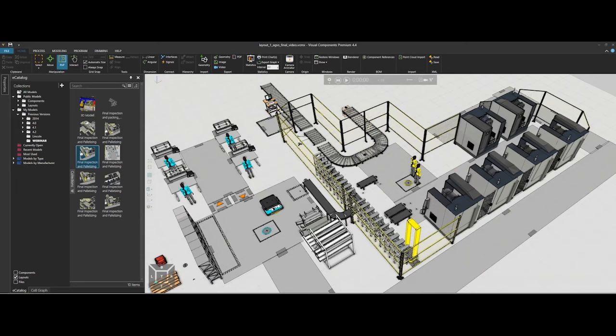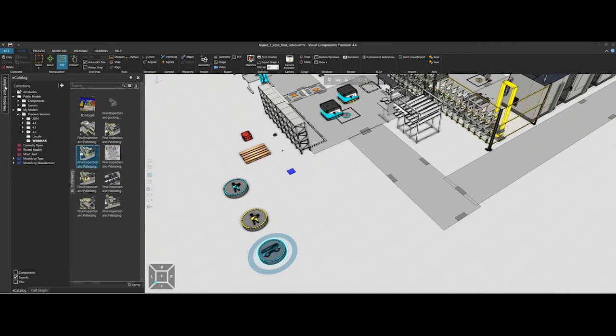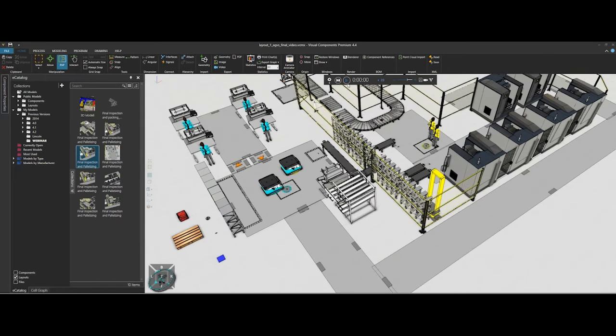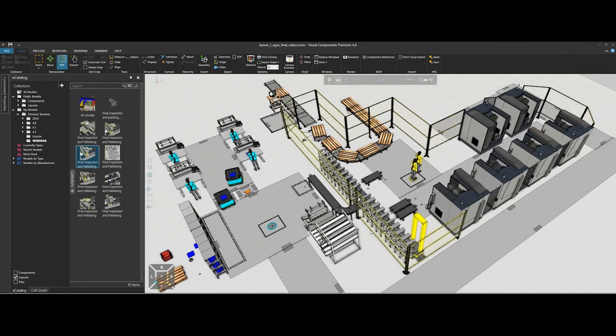The advantage simulation gives you is you're able to do something this easy. We're able to take this, copy it, and you see I'm doing this real time. I simply added another one. I'm going to go to the AGV controller and add the resource. I'll hit play, and now we can watch that same scenario, the same process, but now we have two AGVs instead of one. In this case, it took me about 15 seconds to figure that out. And I also will see that there's a 4% increase in production based on this.